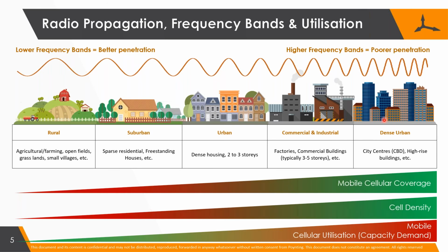The other aspect is that capacity there becomes an issue. Most of the problems that you find are because the cell base stations don't have the capacity to handle all of the data that's required. And that's one of the areas where external antennas help a lot, because you give the cellular operator much better spectral usage. So you can steal quite a lot of his capacity. He's going to prefer serving you to other users accessing the network at a very slow data rate because of the low signal to noise ratio that they will have if they don't have proper antennas installed.